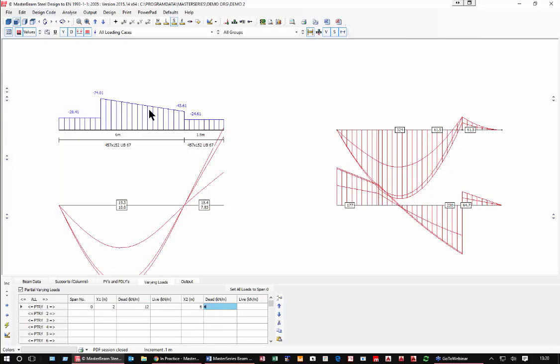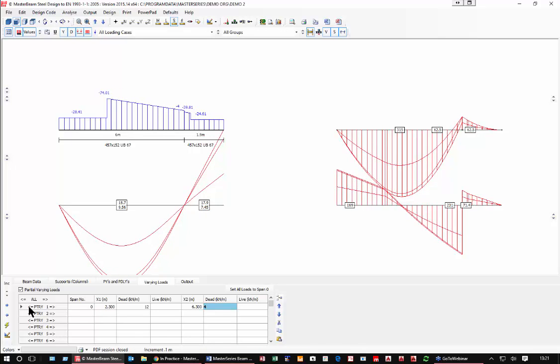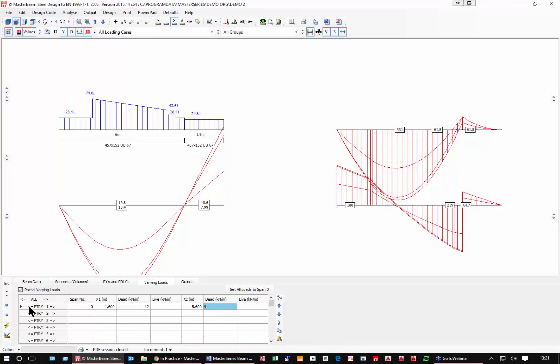So it's adding on here from 12 down to 4. And as I now move this 100 mil at a time, I can see it moving into the next span again dynamically. Now, the quick and smart of you will have spotted, because this is a 2-span beam and we're doing envelopes, loading here has to be maximum when this is minimum, and vice versa. Well, when we do our loads this way, we don't have to worry.